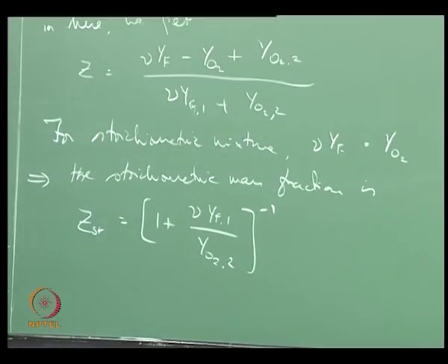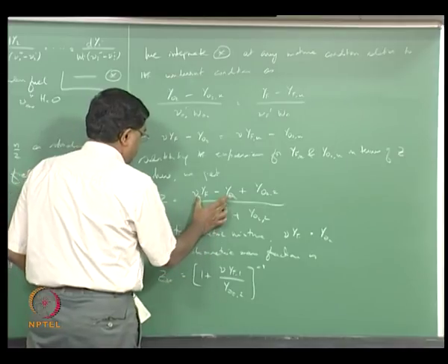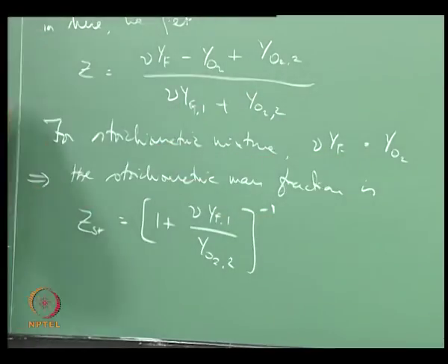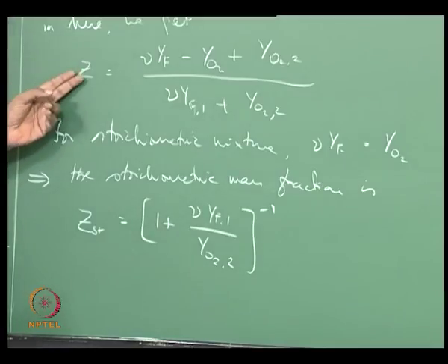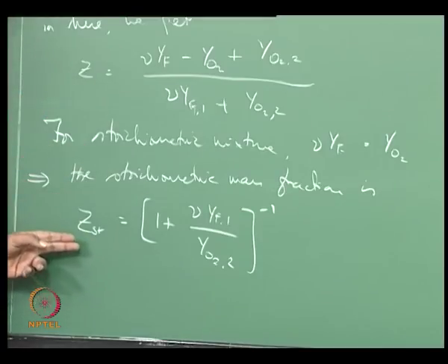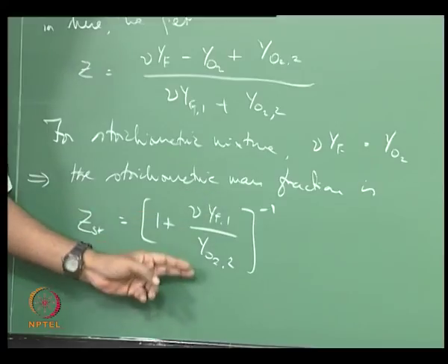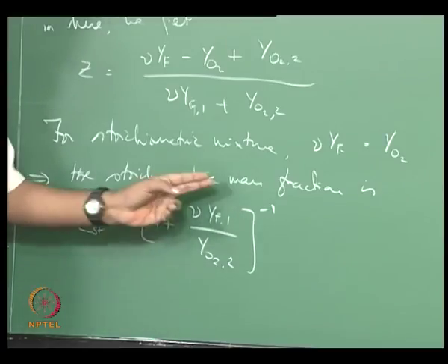I should be able to show that, right. If you now say this is going to go away, then you rearrange. What this tells us is there is a particular value of Z which is the stoichiometric mixture fraction naturally, and it is related to how the inlet stream mass fractions of fuel and oxidizer work out, right.